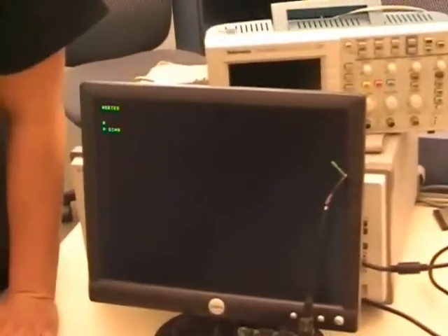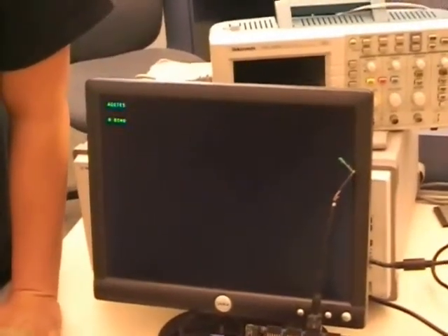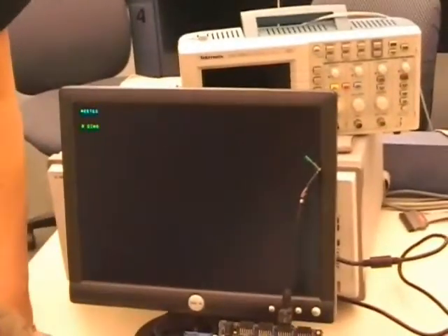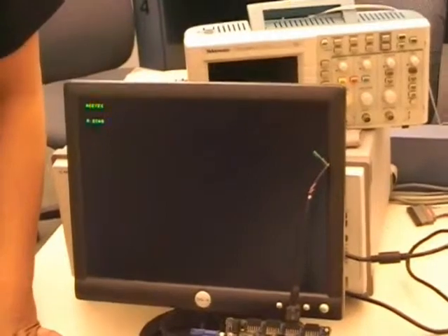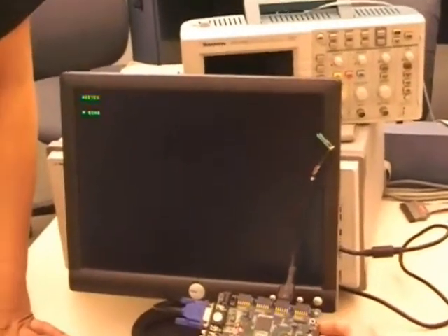You'll also notice that on the Nexys boards themselves, you see the little LEDs flashing. Depending on whether you're transmitting or receiving, those are the physical ASCII characters that you're sending. If LED 6 is on by itself, it means you're in receive mode. If LED 8 turns on for a moment, it means you just switched over to transmit mode.